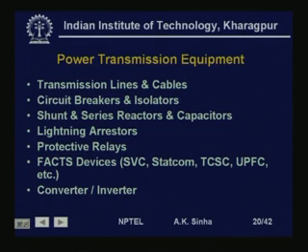Then we have protective relays which disconnect the transmission system when there is a fault in any part of the system. So, they identify which part of the system is faulted and then isolate the fault as quickly as possible. These devices work very fast, of the order of milliseconds, that is, in less than 20 to 50 milliseconds they are able to isolate the transmission systems. FACTS devices, as I just told you, use power electronic devices. We have different kinds of FACTS devices which can control power flow on the transmission system and maintain the voltage at various points in the system.